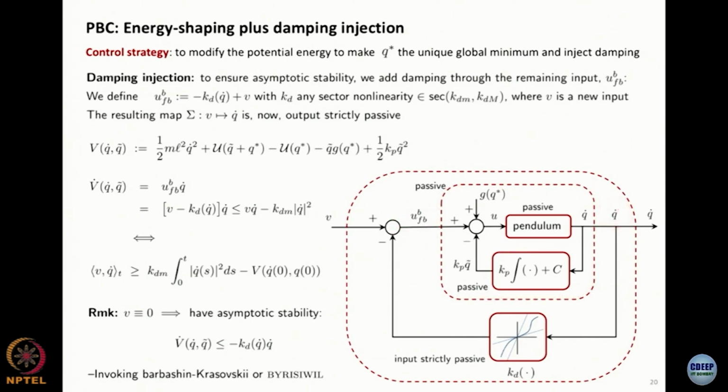Q dot. And remember that theorem of Byrnes-Isidori-Willems. It was saying that if I have a passive system and I have that detectability assumption satisfied, all I have to do is interconnect an extra feedback here, which is basically a function of the output with respect to which my system is passive. And this function here should be basically a nonlinearity living in the first and third quadrant.